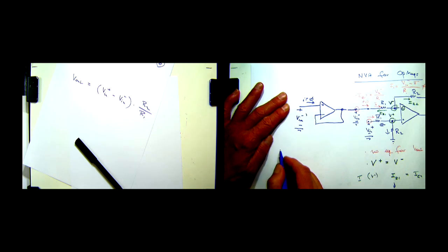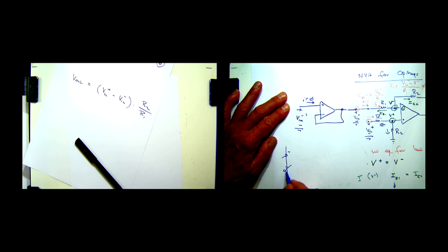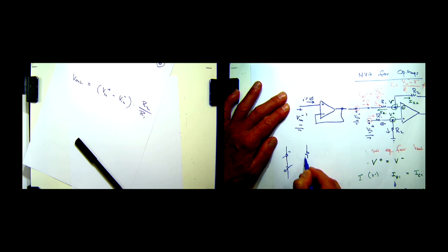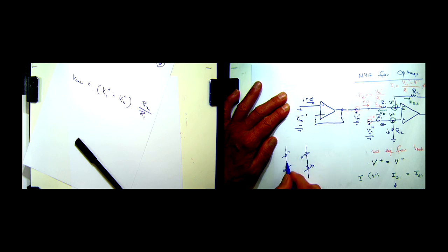And if you had a bridge circuit here, we've had these bridge circuits, right, where the resistors measured something, for example, the weight of something, and then you analyze this circuit a million times, VDD, VSS, or whatever. And you want to know this voltage here, and you want to amplify it. Well, you can use this circuit for doing this.